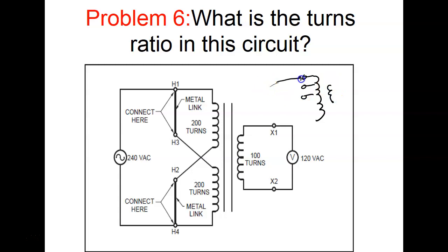And so when they bring it in, they hook it up, and what they're trying to get over here is 240. What we have on our house is what we call a center tap transformer. So up on the power pole, we have this. We have a wire running here. If everything was perfect, we would have 240 across here, and then between here and the center, we would have 120. They take this and reference it to earth ground.